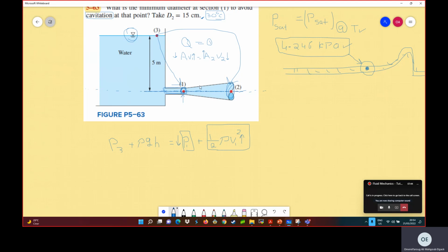And for this, here the cross-section starts to vary. The area starts to increase until we reach the maximum area here, and that maximum area is associated with the maximum pressure, P max. Because higher area will be associated with lower velocity, and lower velocity means that you have higher pressure.